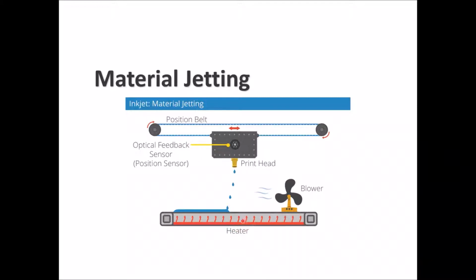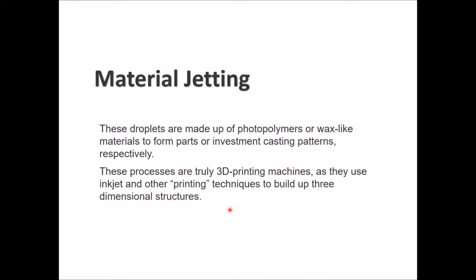In the base we can see there is minimal heating, not overheating that can melt the material, but heating that keeps the material flexible enough to accept the coming material into the old material. When you deposit material and let it cool down a little bit, and then put new hot material into it, they will not be homogeneous as one object. So this heating pad on the bed of the 3D printer keeps the base or original material warm and flexible enough to accept new material being added into it.